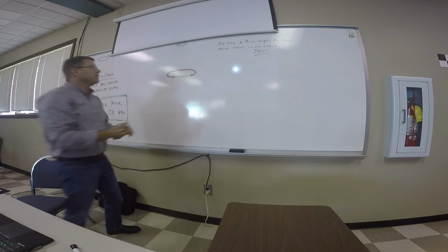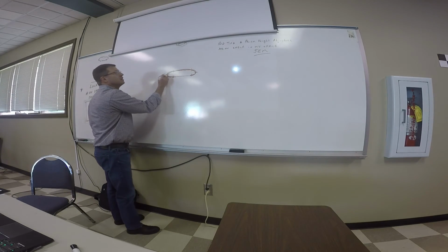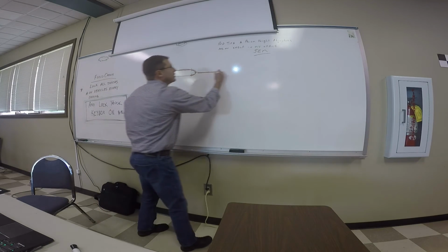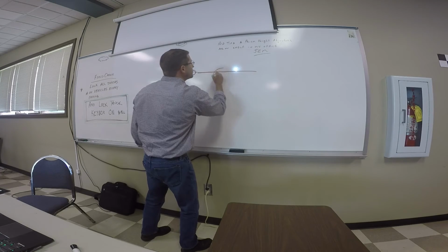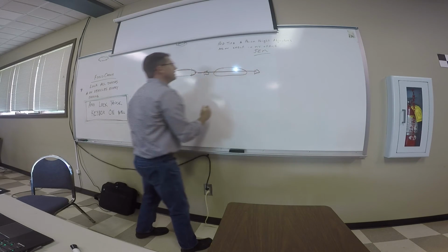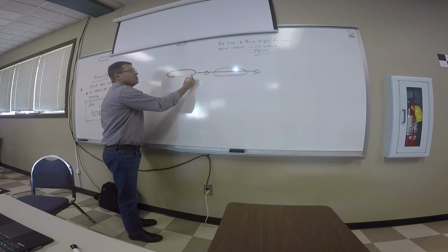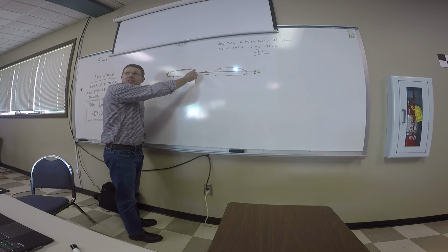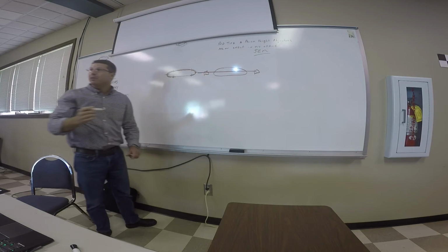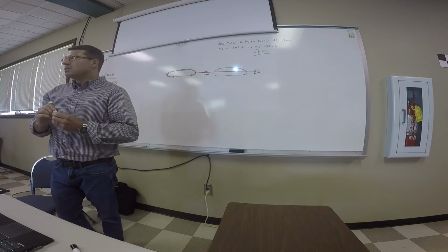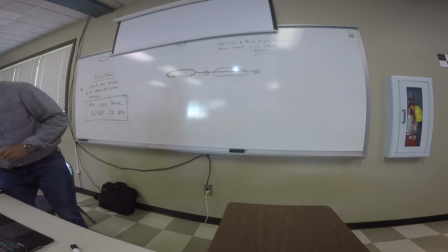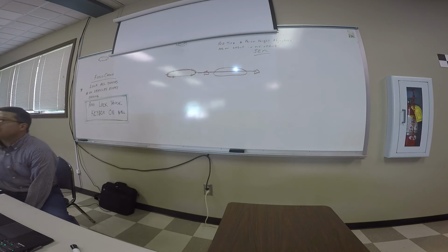Now that's assuming that your low points aren't right here running through your parking lot, and that this right here is a low area, and you've got all these curves, and they've got drop inlets or something like this. You don't want to be shooting this and miss these low areas, when all you'd have to do is pick them up with a curve shot right there. You may need it for a Z. Exactly. But for horizontal as-builts, you don't have to shoot all those extra curve shots.